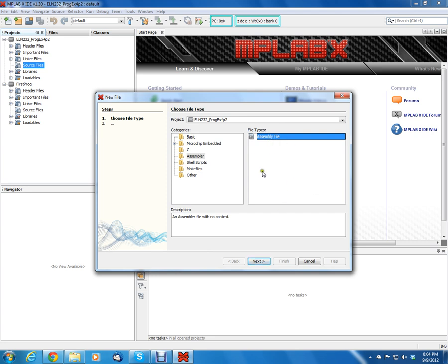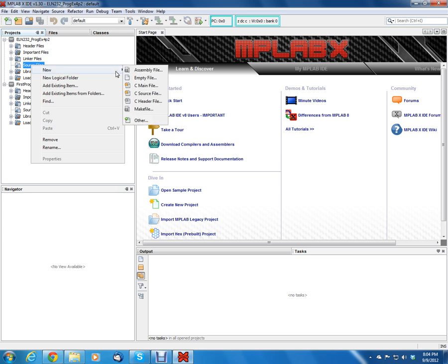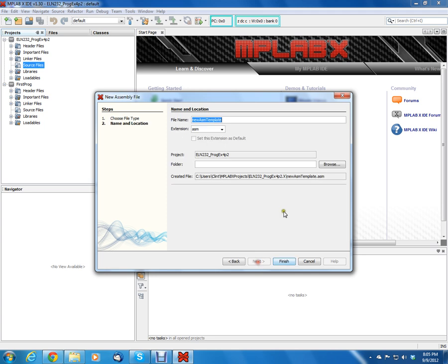After you do that for the first time, it'll actually put it on the list for you. Let me just show you that one more time. Let me just cancel that. I went a little bit fast there. So for source files, say new, and at first that will not be there, so you say other, and then in the categories you click down on assembler. You can program in BASIC if you want, or C, but we're going to do assembler. So let's do assembly file, and then we click next.